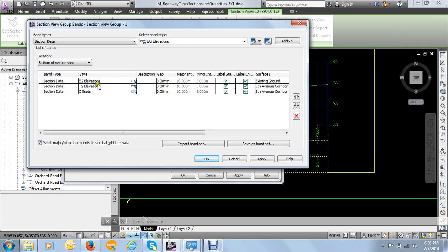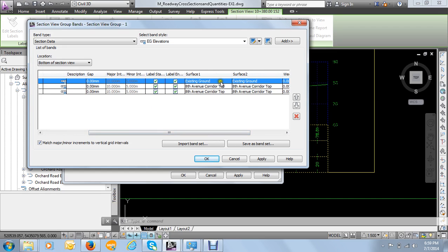Under this, the first line shows the existing elevations, and the second line shows the finished ground elevations. So when you move to Surfaces, for the first one, at the beginning all were just the top. That's why they resemble. Because the first one is the existing, you have to change these surfaces to existing, then existing, and then you apply.